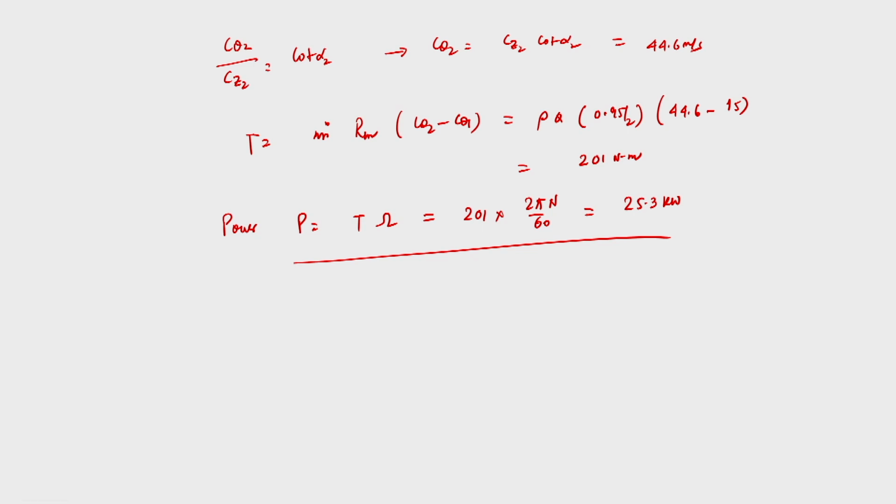So, with this probably we have understood how we need to solve the problem for an axial flow machine. Essentially, for an axial flow machine, flow areas at the inlet and outlet are equal, which gives that flow velocities at the inlet and outlet are equal. From the given data we have to calculate different components of velocities: the tangential component of absolute velocity at the inlet and outlet, and the tangential component of relative velocity at the inlet and outlet. From there we can calculate all other quantities, and we have solved the problem.